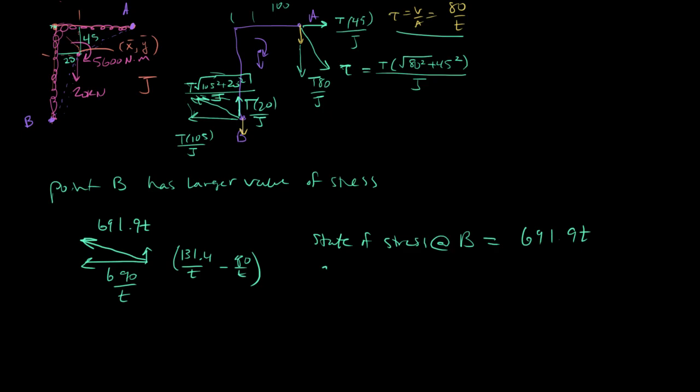If we select a safety factor equal to, say, 2.5, then this allows us to calculate the thickness of the weld joint, because we are told that we have an E60 weld rod, and that gives us a 60,000 PSI strength.